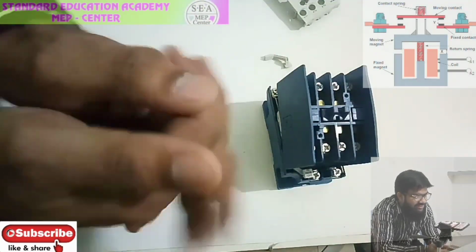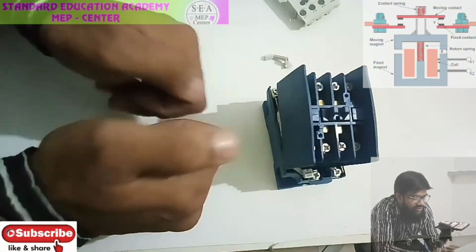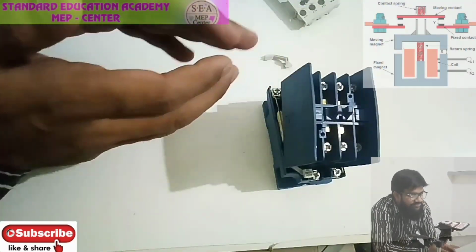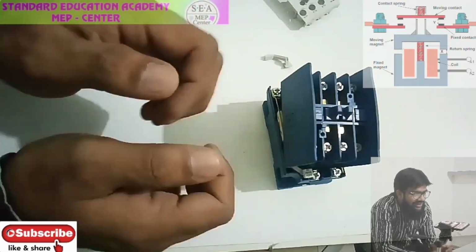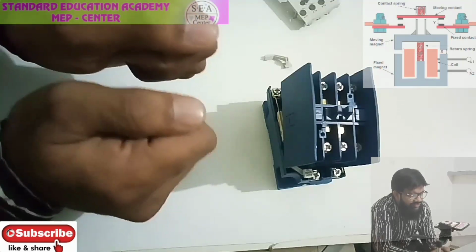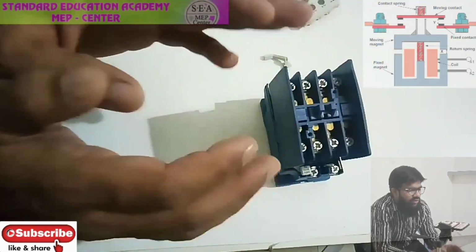Energizing the coil is done with single phase, and the supply to turn on or turn off a particular three-phase big load is with the help of a single phase. With this, we will be avoiding the major sparking and many issues of a three-phase load with the help of this contactor. That's how a contactor works.